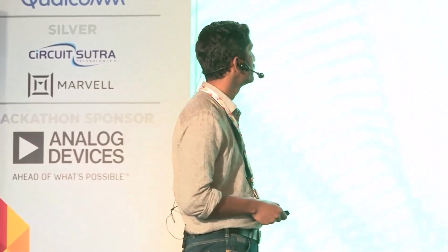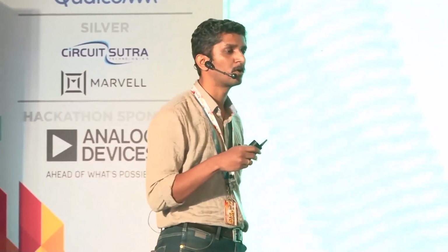Why did we start employing these auto formal checks? Basically, we wanted to test it on our legacy IP and prove the concept, and later use the same auto formal checks for all our new features. To prove that, we knew there were some issues, so we showed that auto formal really catches them, and that the tool is really working and not throwing false violations.